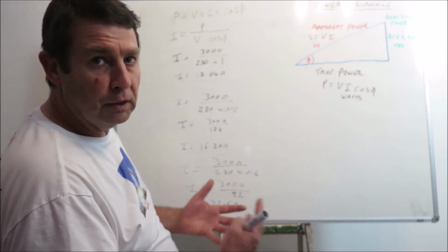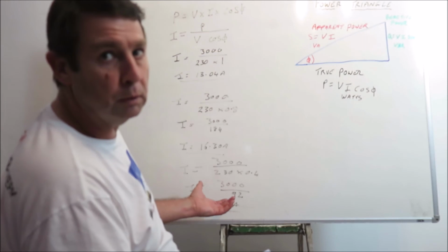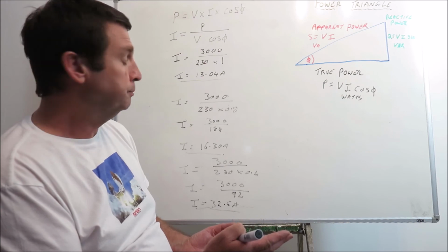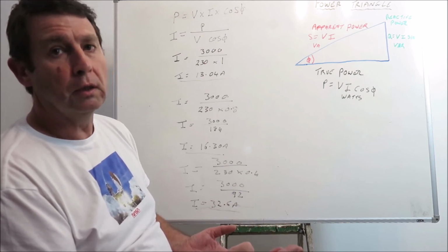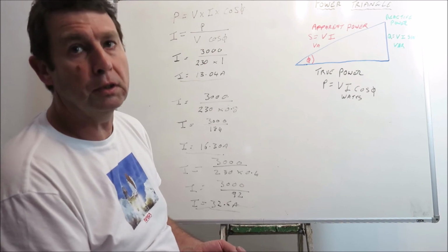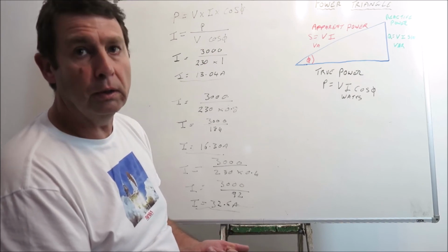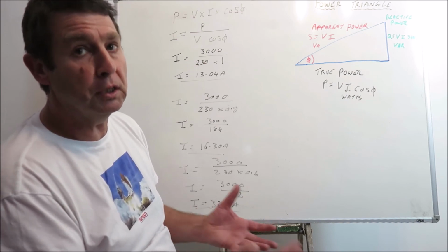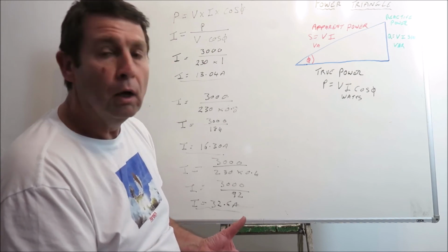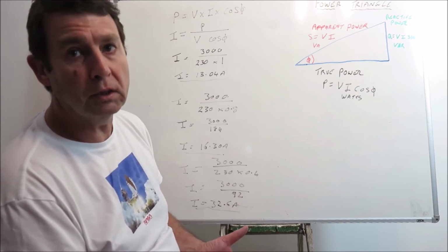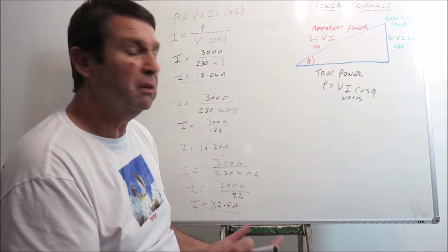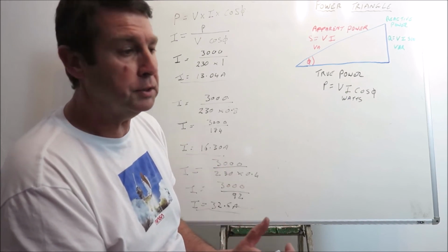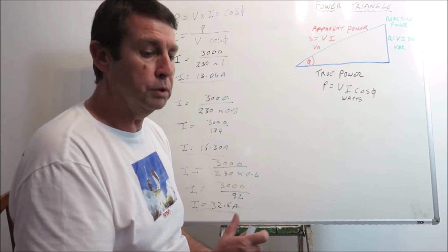So I kind of answered the question a little bit there, as well as how do we correct a poor power factor. Now we know that the power factor lags with an inductive circuit and a power factor leads with a capacitive circuit. So what we have to do is put in power factor correction capacitors. Now these capacitors can either go in at the service intake position, where you can have capacitor banks. Sometimes they can be switched in and out by relays depending on the load as well. Or you can connect them locally. So if you think about fluorescent lighting, it's got a power factor capacitor connected in with it. Also motors and things like that. You can have the power factor capacitor connected at the motor terminals.